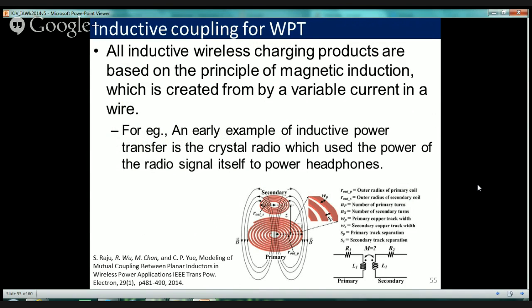As I mentioned, it is also possible to work at much lower frequencies and do a coupled power transfer. A coupled power transfer is almost like the transformer principle, except that rather than having the fields confined using magnetic lines confined using the metal core, here it will be like an air core transformer.